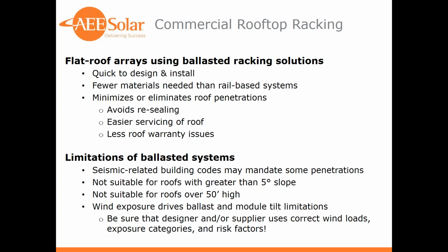For slopes greater than 5 degrees, we have gotten some approval for over 5 degrees, between 5 and 10 degrees, but we do see the ballasting or need for penetrations in doing those. But the sliding forces tend to start to get too high on roof slopes that are greater than 5 degrees.